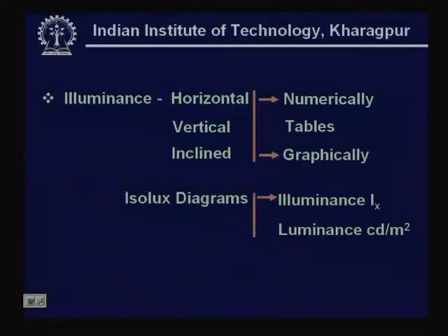So, what do we have? We have the illuminance, which is a very important thing. Depending on the nature of the work plane, horizontal plane, vertical plane and sometimes inclined plane, this data is available in the form of numerical values which are tabulated or graphically in the form of Isolux diagrams. Illuminance here has been abbreviated as Lx.